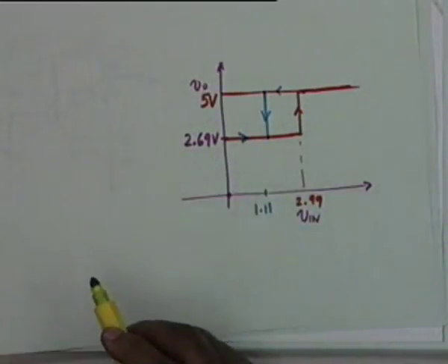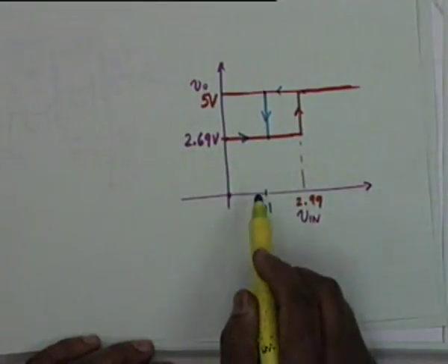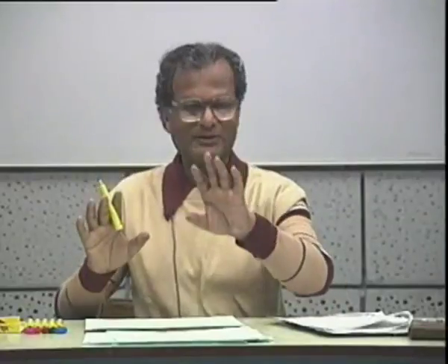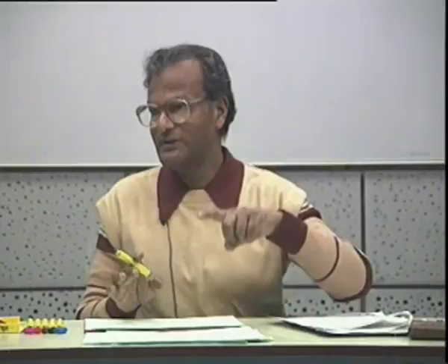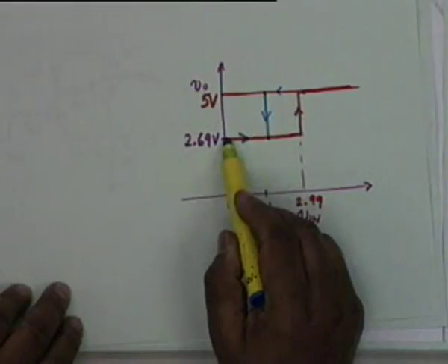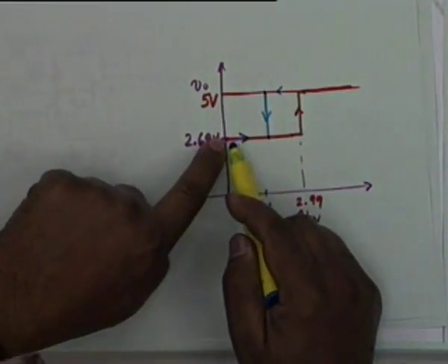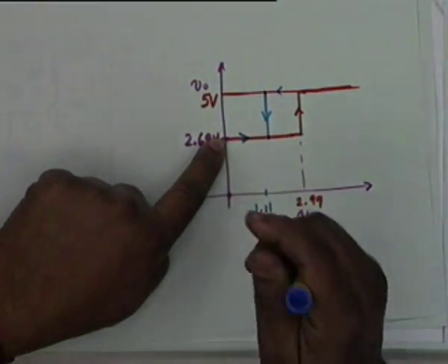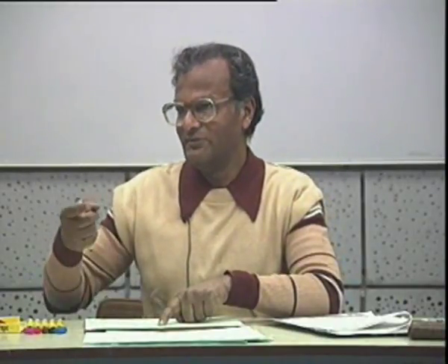Alright. So if I show the direction in which I went, I increased. Initially the power supply was put on, Q1 was off, Q2 was saturated, and this is the condition. Then I increased V in. How did I reach this condition? Initially the base of Q1 was connected to ground, 0 voltage.